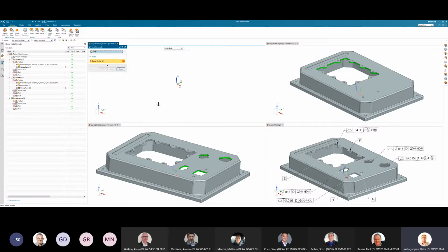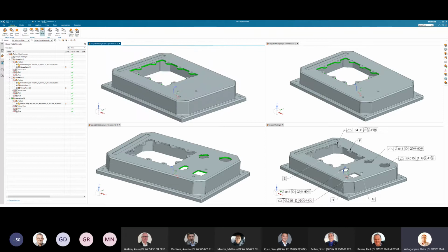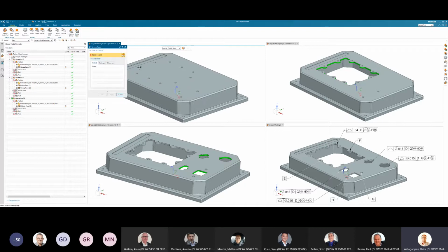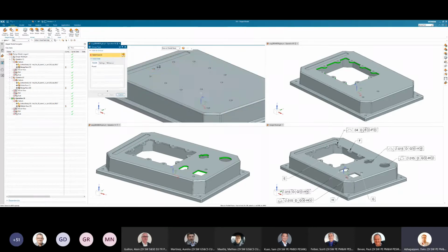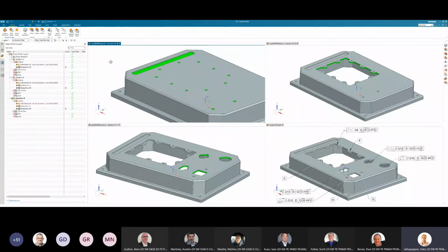So click on this, I can select the operation 20 information. And then obviously I'm going to delete these pockets, the center pockets here. And then I can identify the faces, so I pick all those holes with equal radius here. The radius, so pick all of them and then identify that as the feature that I'm going to be mentioning here.